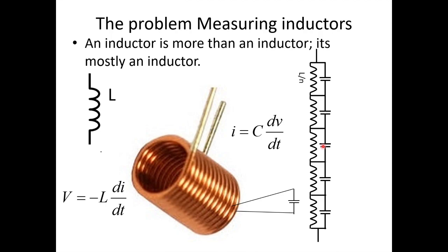One of the ways to defeat this capacitance is to understand how the capacitance works. The capacitance, this C, will transfer current between the different loops of the wire based on the voltage change between the loops of the wire. This dV/dt, for those who don't understand differential mathematics, means the change in voltage as a function of time. So you take your voltage change, multiply it by the capacitance, and that'll be the current that is coupled from one loop to the other. Some people call this displacement current. I just call it capacitively coupled current, whatever.